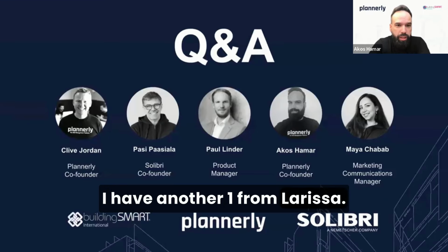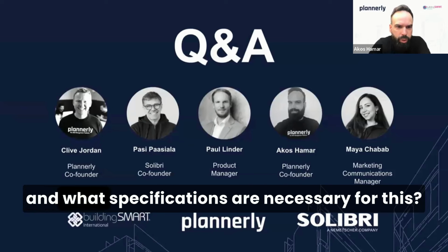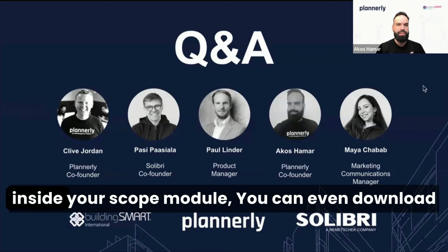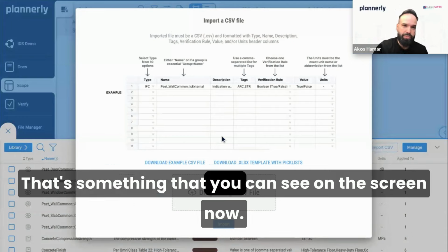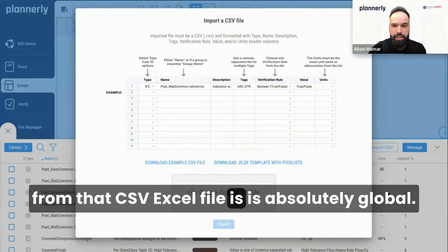I have another one from Larissa. Is there a way to import existing information requirements into Plannerly, and what specifications are necessary for this? So actually, if you go to Plannerly and look into the information requirements tab inside your scope module, you can even download an example of how it has to be formatted. That's something that you can see on the screen now, and then just importing it from that CSV or Excel file is absolutely doable.